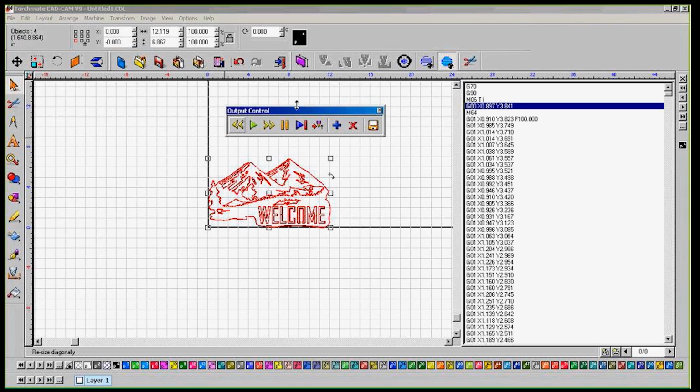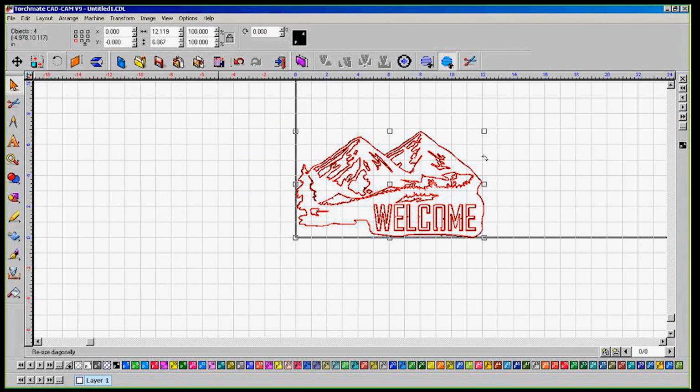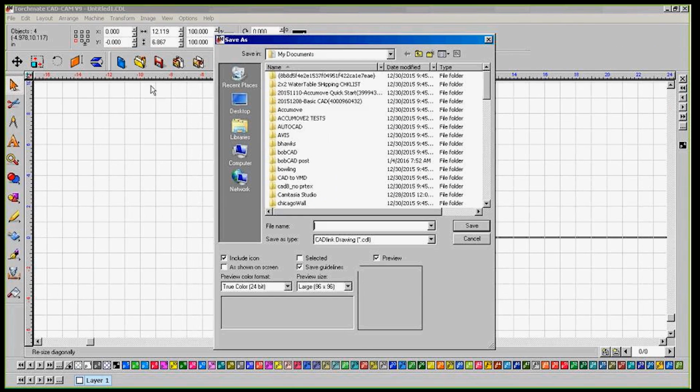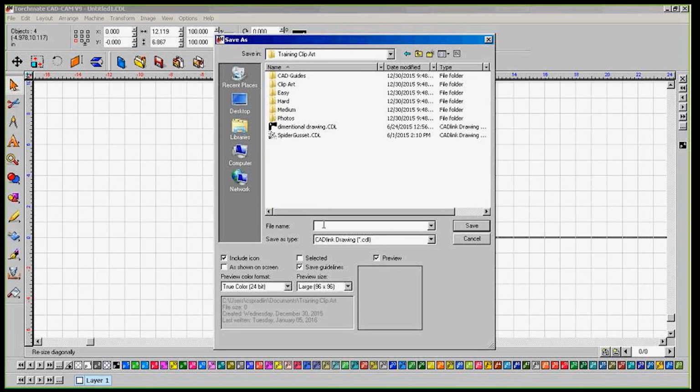If you've kind of played around with it a little bit, you will notice that if you do a select all on something that does have those straight lines, it will create some real funky toolpaths. That is because the software doesn't know where to put the curve correction and the lead-ins if you select a male or a female toolpath. That's why you want to separate them away from the rest of your design and do an online toolpath instead of doing male-female on those.